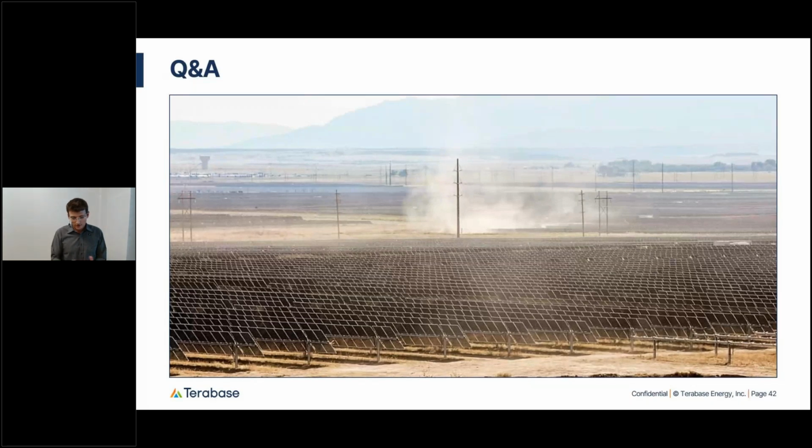Yeah, I do. Great question. So let's say if I was developing projects, I would of course use PVRADAR first. The first question is, is it needed to make soiling measurements? And the answer depends on the site. As I mentioned throughout my presentation, if you have a site like this open plane, and you build a power plant in the middle of it, you can assume that the soiling conditions will be fairly equal. Therefore, our estimates will be very good.